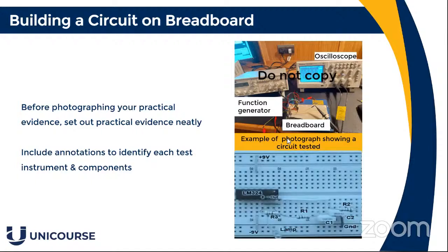Here we're looking close to the breadboard. You can see here a chip. It's not the same circuit as the one you'll be building, but you can see where it's been set up, and you've got in the center there where there's no connections, and the resistors are at the bottom here, and you connect up the power supply at the top there, which could be your top rail, and your negative rail at the bottom here through this rail over here.